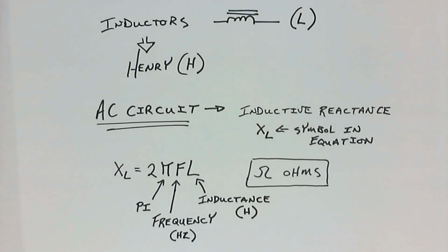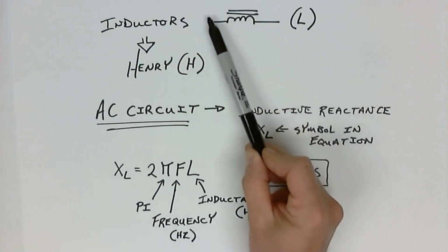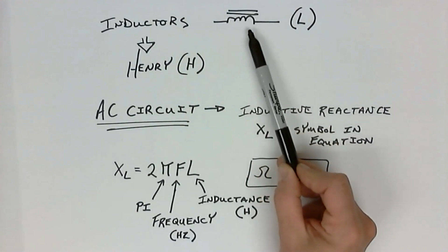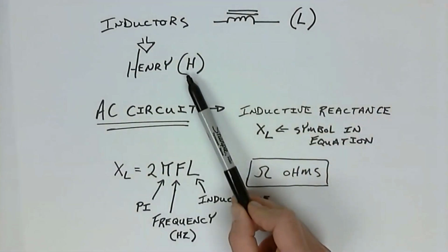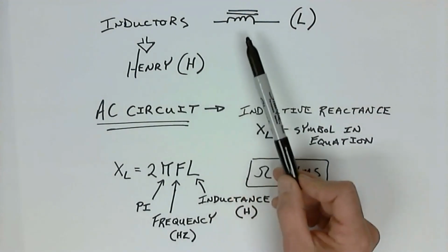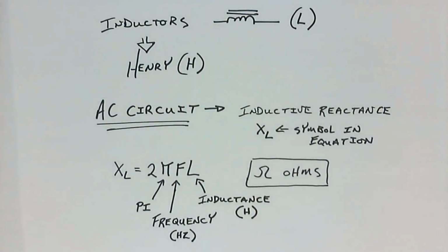So what we have with an inductor is something that is a structural item, something physical, that the henries cannot be adjusted unless you physically adjust something on the inductor itself. Remember, the inductance of an inductor has to do with the number of turns, the type of core, the permeability of that core, and the length of the magnetic field. When we're dealing with an AC circuit, the way in which an inductor reacts within it, really the only thing that's going to adjust this is the frequency.